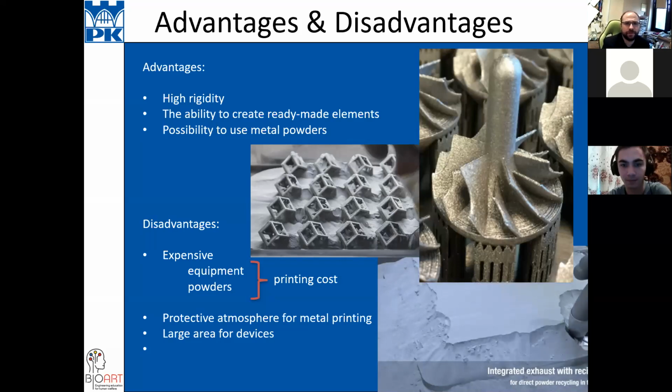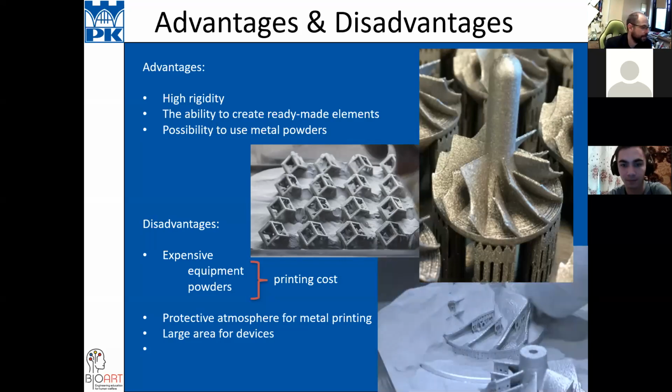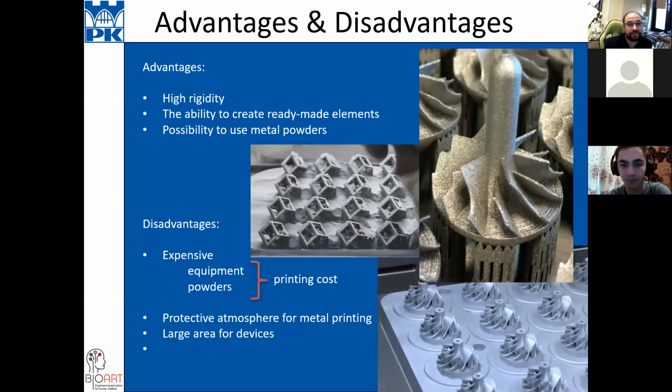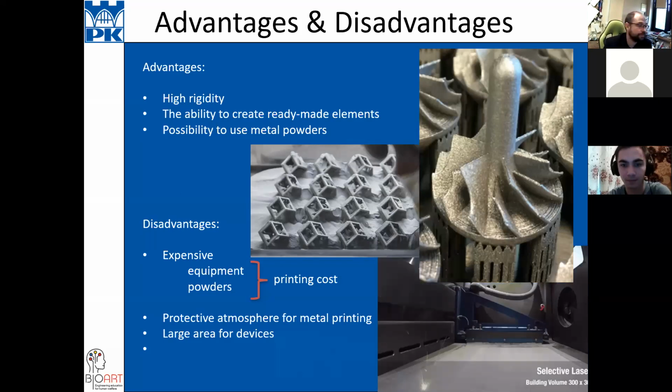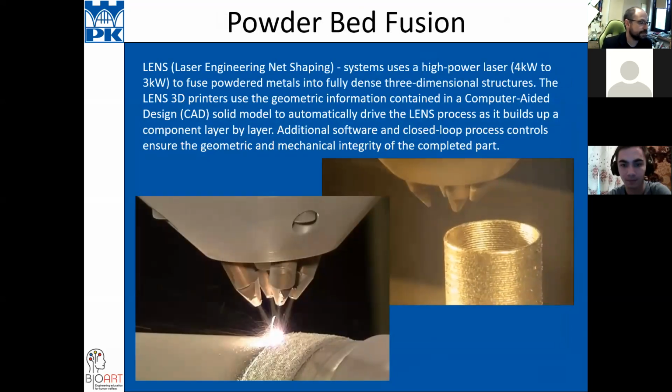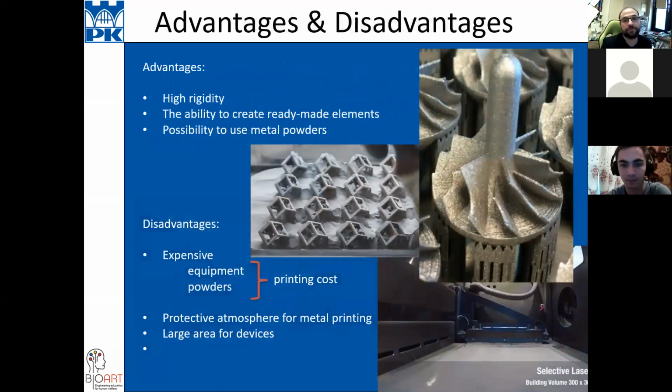But for example, in our laboratory we use pure hydrogen for sintering. It's a very good quality of sintering material. The same situation is here, and also after printing you must sinter this material. Of course, in this metal you have some kind of selective laser sintering, but sometimes you must do some heat treatment. It's good to minimize the stress of the material after printing.